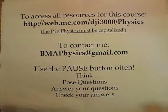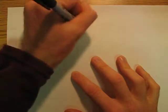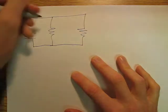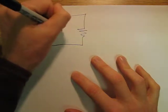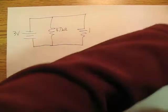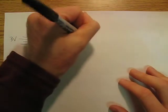And so now we're going to jump right in, and we're going to basically use the same resistors, but we're going to do a 2 resistor parallel circuit. So we're going to have our same 3 volt battery, and this time my resistors are going to be in parallel. 3 volts, 4.7 kilo ohms. I'm going to swap out. I think the 2.2 is going to work a little bit better for what I want to do.